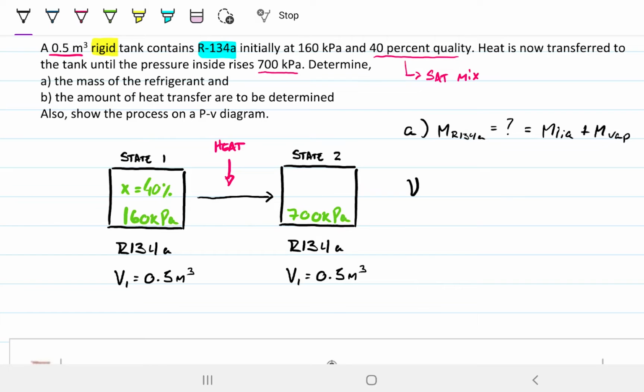As you know, this is one of the thermodynamic properties, right? In this case, because we know it's a saturated mixture, it's going to be a combination of both the specific volume of the saturated vapor and the specific volume of the saturated liquid. All these things we know already from prior problems, from understanding how pure substances work. So in this case, it's just the saturated vapor times the fraction of saturated vapor that I have, which happens to be the quality. And whatever is not saturated vapor, that is 1 minus x times my saturated liquid.